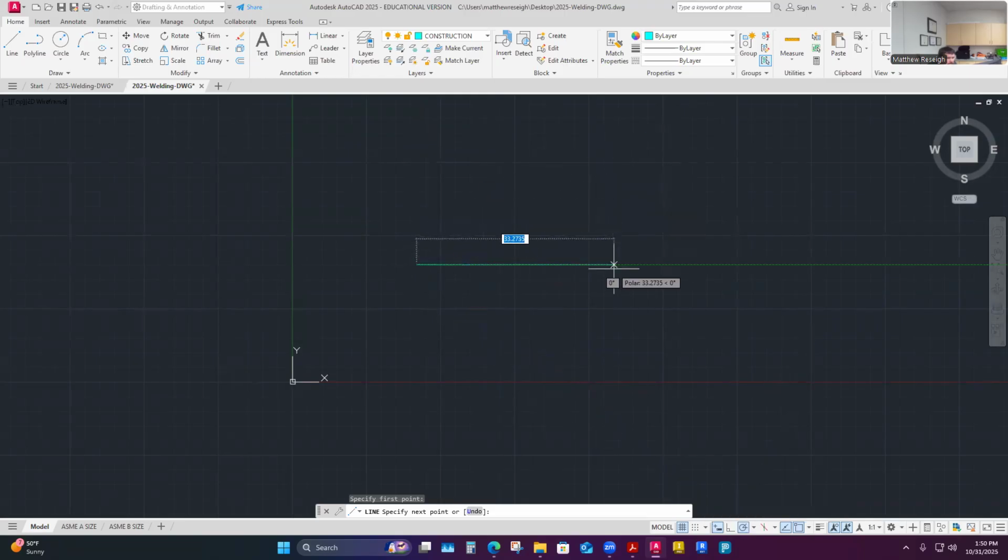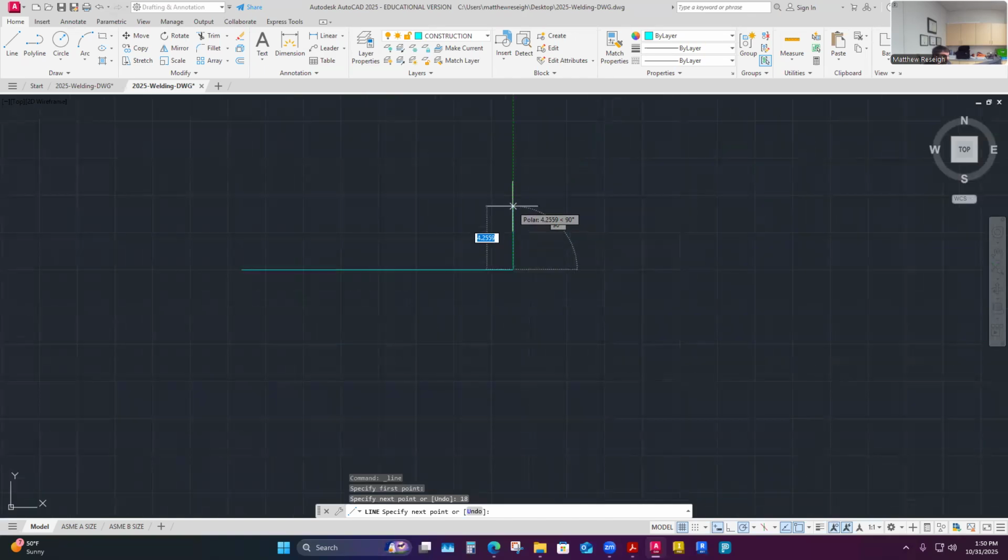So I'm going to draw this rectangle boundary totally vertical and horizontal. In this direction, it was 18 inches, enter. So I just enter the number while I'm in there. I've snapped the line, and then I just left clicked once to start the line. As I pulled away in the direction I want to go, I input the data with the keyboard.